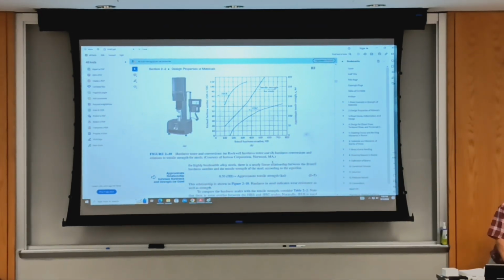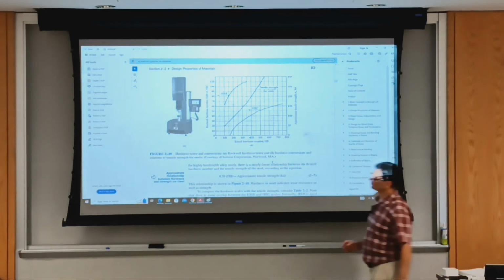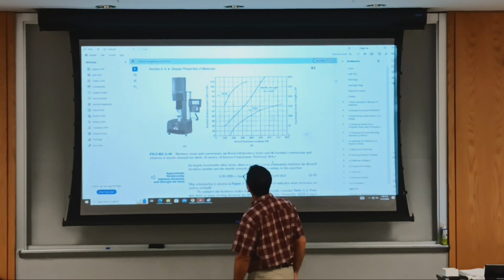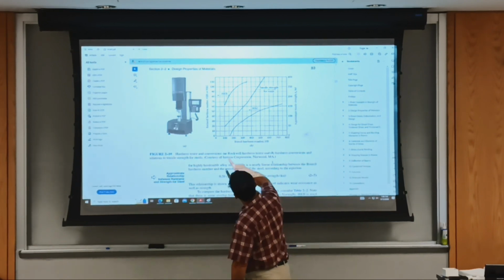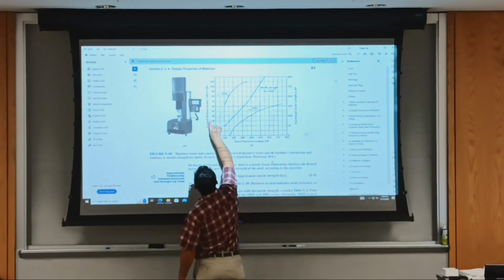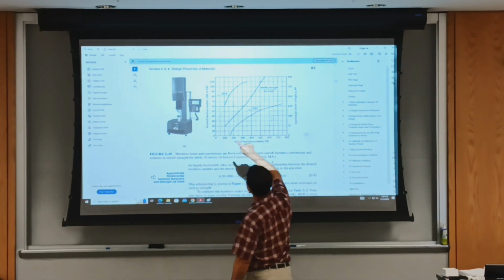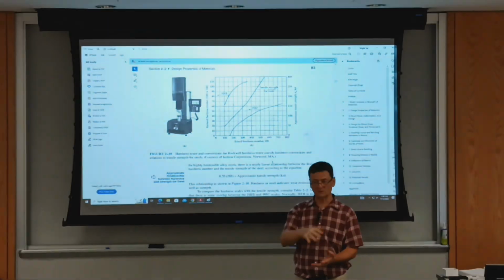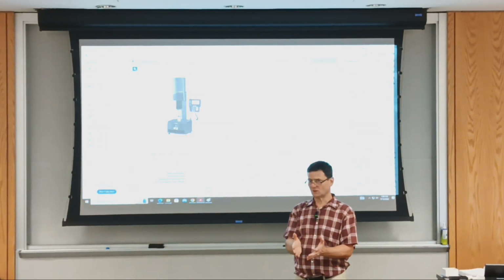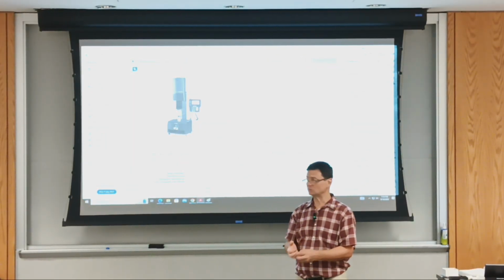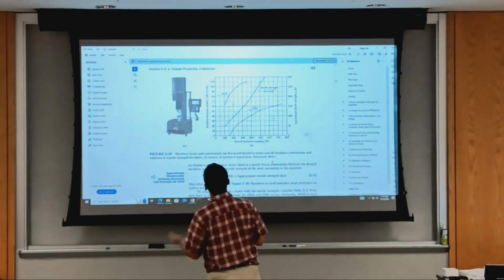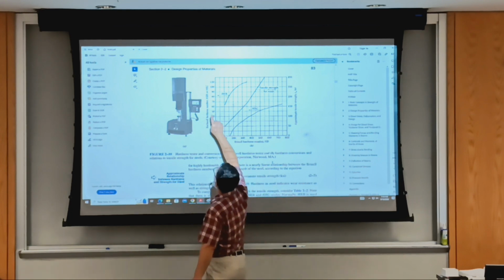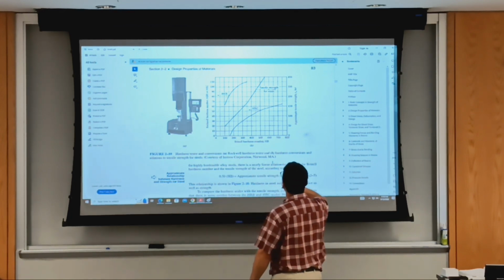Okay, so there are various test procedures and hardness scales. So you can see here Rockwell hardness, Rockwell B and C. It depends on the amount of force applied. If it's a soft material and you put too much force, you need to anticipate the hardness to choose the right procedure and the scale for it.